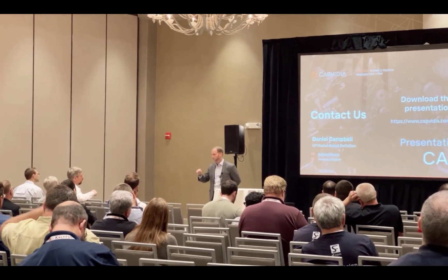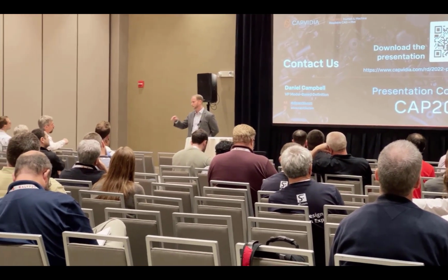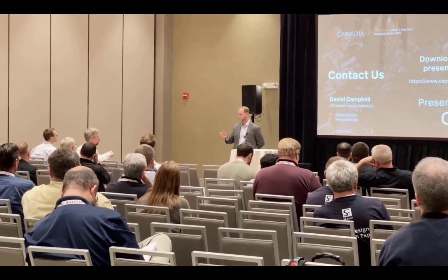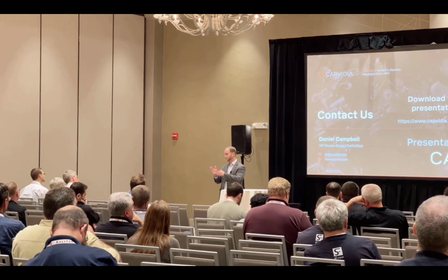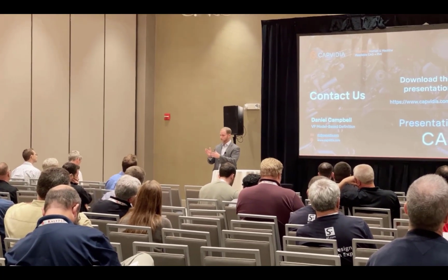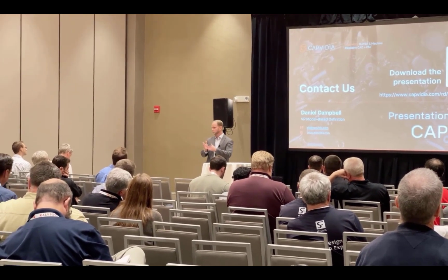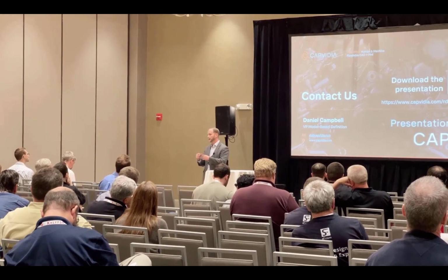They're making the same part over and over, and as they watch the trends on the quality controls, they put manufacturing tolerances on them, X and Y direction deviation on certain things, and as things start to drift, they'll adjust the machine tool program to correct for that.